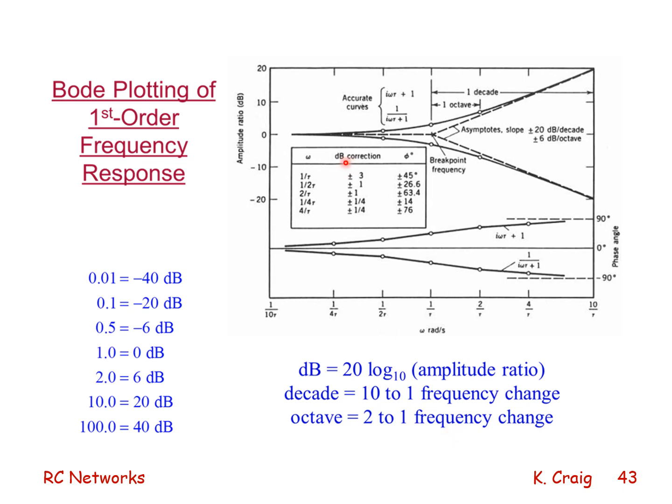And we show here, if my transfer function is 1 over tau s plus 1, my Bode plot looks like this. It starts out flat, bends, and approaches minus 20 dB per decade in slope. The phase starts at 0 degrees, goes through minus 45 degrees at 1 over tau, the bandwidth, and then approaches minus 90 degrees.